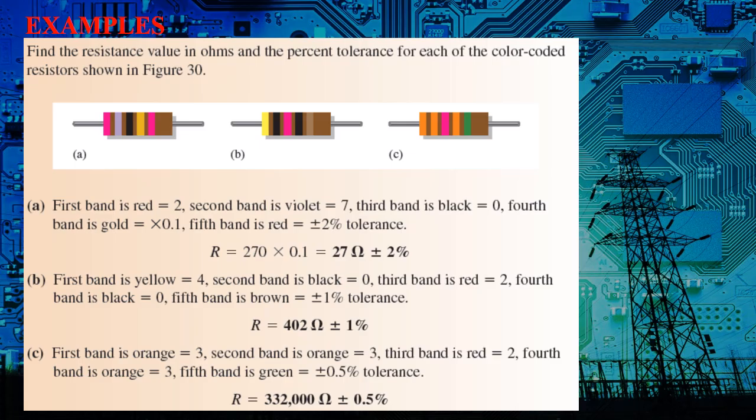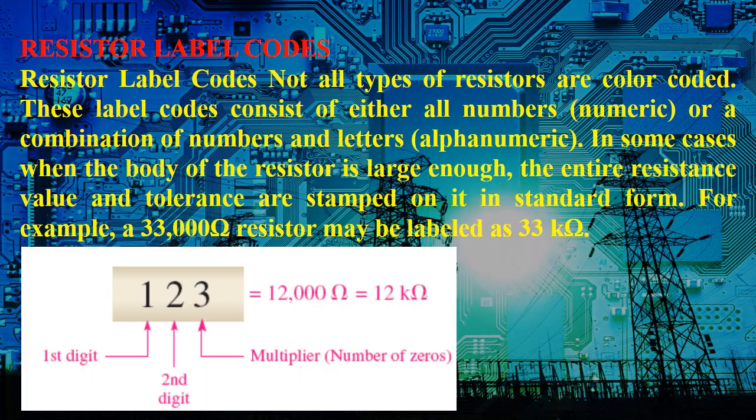So when you take the measurement, it must range within plus or minus 2%. Because there is error in measurement, that 2% is the tolerance, or it's called a correction factor. If you have any question, you can always raise it. You can look at the second and third examples. The numbers here are taken from the colors, so you can just associate the numbers with the colors and go back to the previous slide and look at the table. That's how you work out the value of a fixed resistor from color.